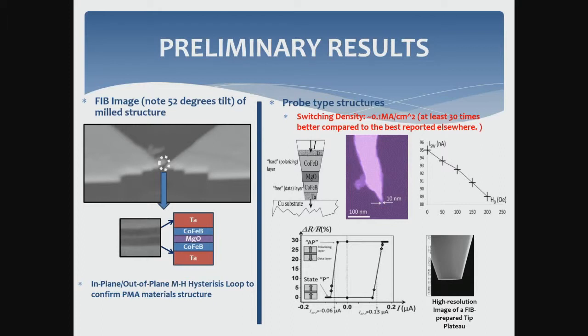So over here, one innovative approach that we used to understand these devices and scale them down to such a small level was depositing the entire junction onto a nanotip, or a nanoprobe. One method that we use is we begin with an STM probe, we cut it and smooth the surface, and then we deposit the entire MTJ here. Once we do that, we further trim it using focused ion beam, and we bring it down to a metallic substrate, such as copper, and we do our IV characteristics.